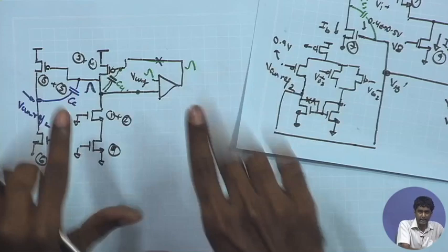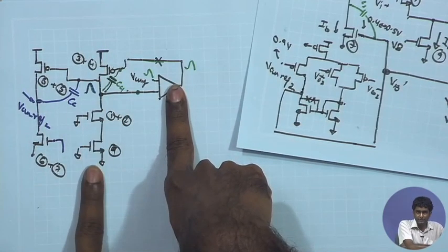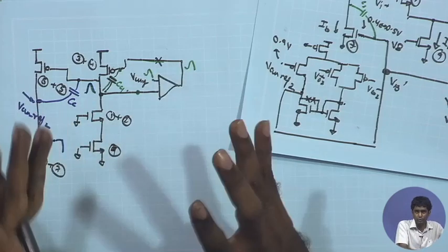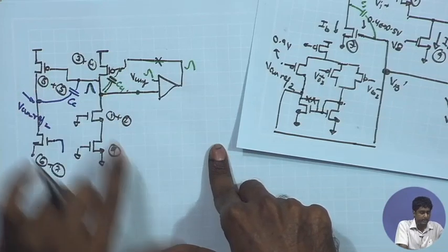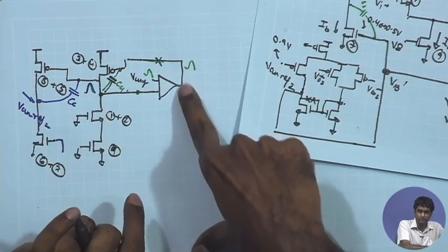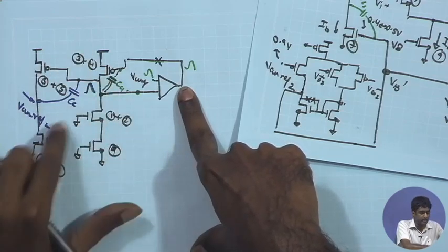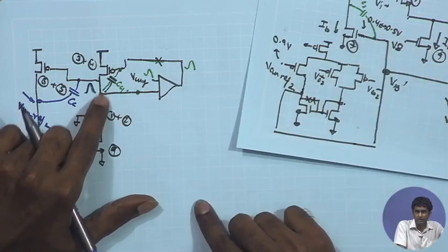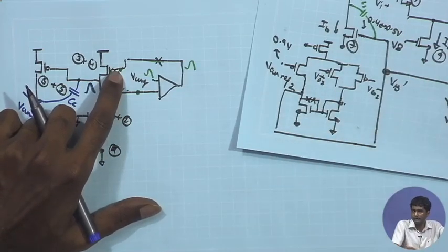So, you should be able to visualize the combination of this error amplifier and the common mode half circuit of the first stage as a 2-stage op amp, which you are compensating with the help of CC1, and as a result it is pushing the pole at the output of the first stage of this effective op amp to low frequency, whereas the second pole over here is getting pushed towards high frequency because of the impedance of the second stage dropping at high frequencies, as we have discussed earlier.